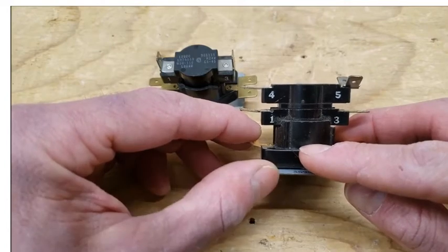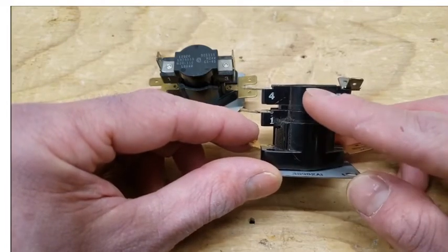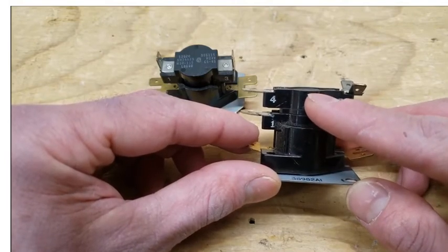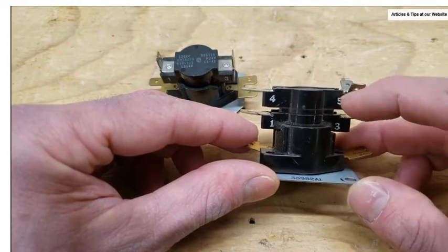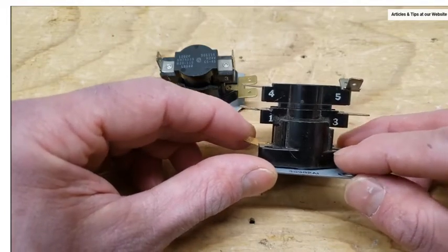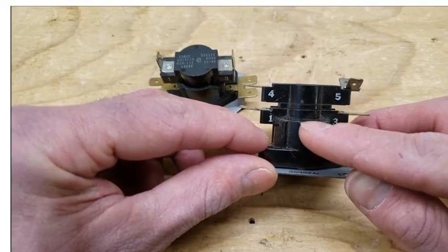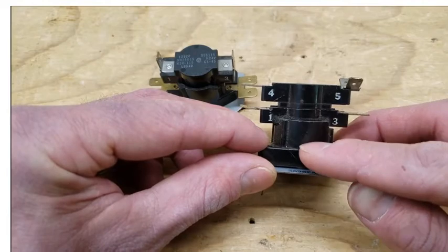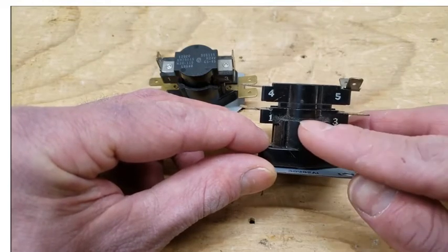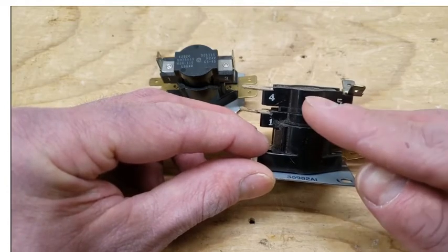And on top of the thermodisc, you have a rod that comes up to 1 and 3 and another rod that comes up to 4 and 5. So that rod is going to normally open the contacts between 5 and 4 and 3 and 1. When the pan gets heated up and the thermodisc flexes, the rod is going to then move down along with the middle of the thermodisc, and it's going to close the contacts between 3 and 1. And then it's going to also close the contacts between 5 and 4.